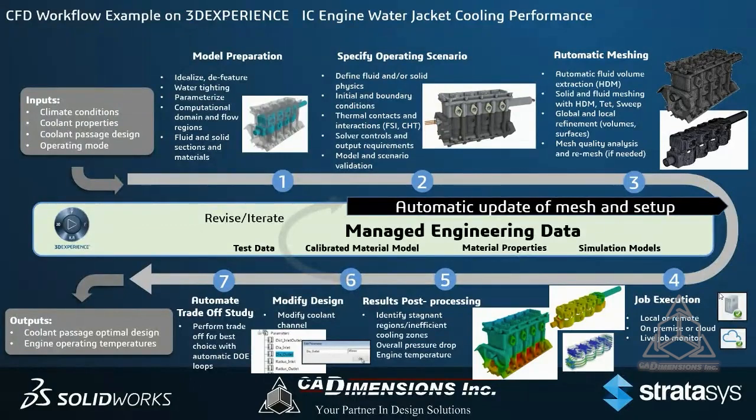So that means you need to have a processor that can handle it. You need to have enough RAM to actually physically build the mesh. We need to basically wait for our computer or the designated simulation computer to chug along on that analysis and get us to a solution. So if we're dealing with really, really large assemblies or meshes with several millions of elements, the cloud solution really shines through because it allows us to calculate those jobs a lot faster than we would if we were solving on local hardware.